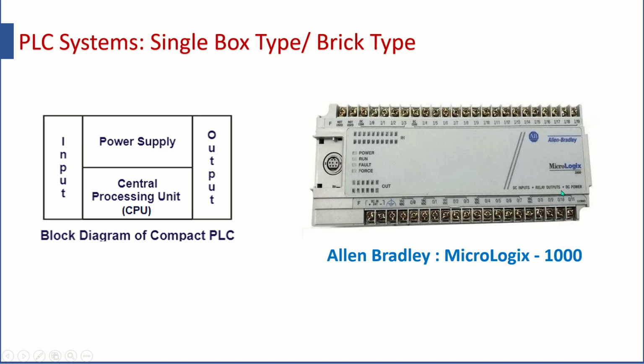Since it is relay output, we are in a position to connect outputs accordingly. Since it is relay output we can connect AC actuators as well as DC actuators. So these are the common terminals. Accordingly you can decide what to do with that.